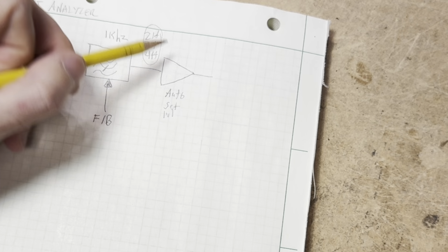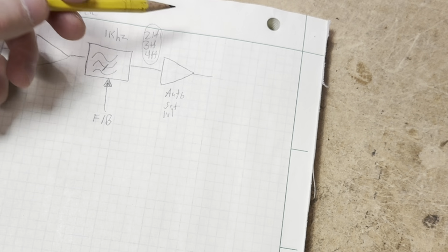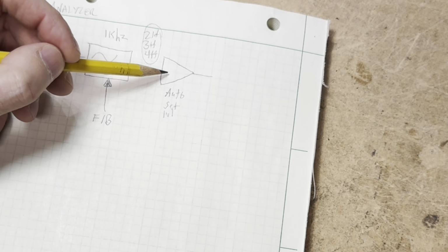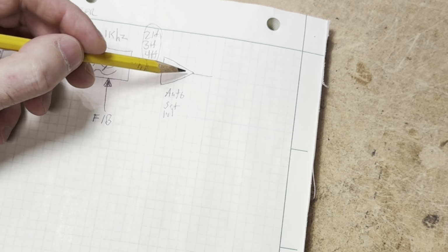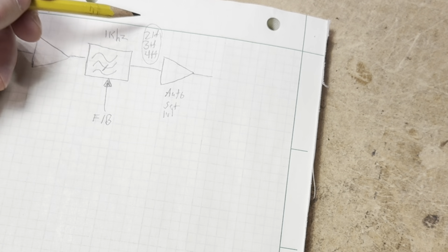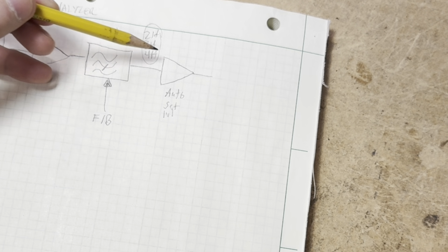It's going to be looking back at the input level, determining what our input level is, and then at the output of the notch filter, it's going to be adjusting the level of the signal going through the auto set level system to essentially compensate for any level changes done by the input system. So it's going to take our input level at the distortion analyzer and normalize our signal levels coming out of the notch filter to the same level they would be at the input of our system.